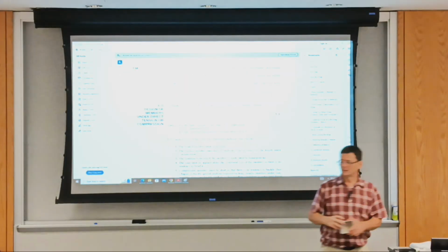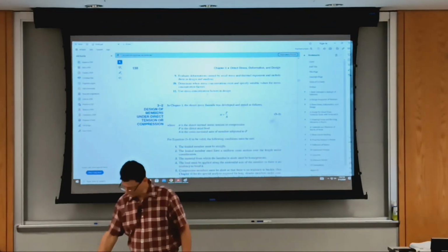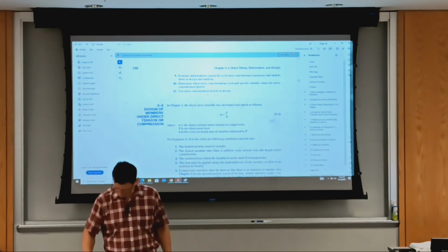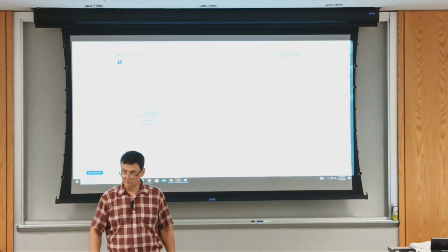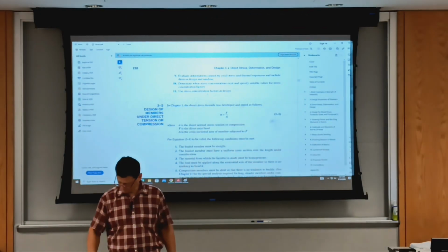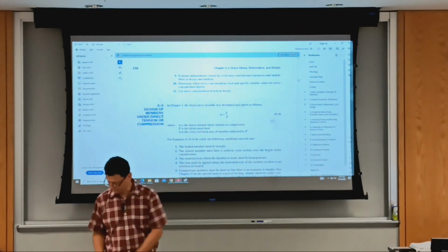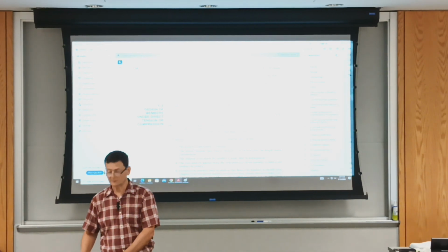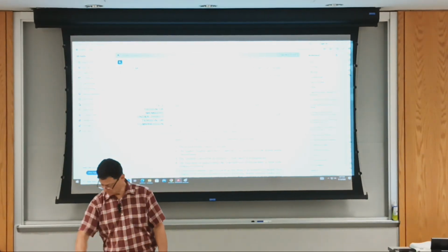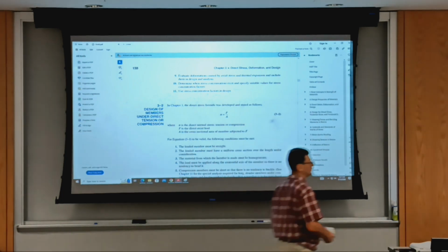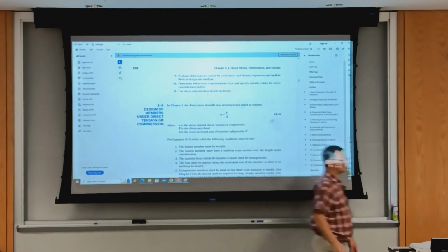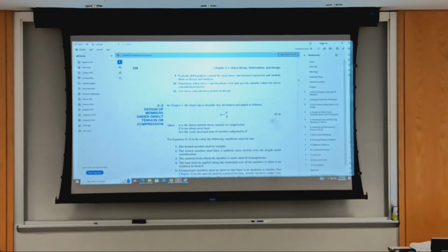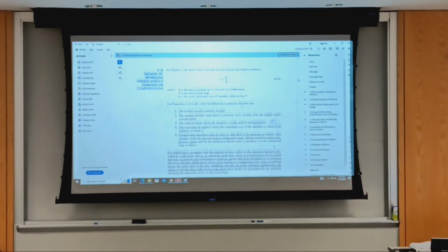So if I have this, assuming this being a specimen, it's one thing to apply the load straight in the middle, but if you put it on a side, you will induce bending. If you tip it, it's indicative that this area here is no longer going to experience stress. It's shifted. The stress distribution in the cross-section is other than a uniform one, which no longer makes this equation valid. You actually have bending on top of axial loading.